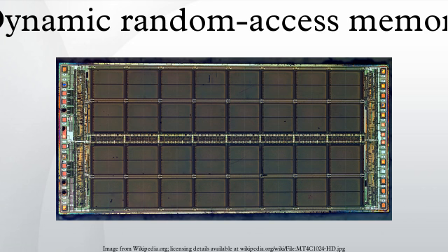BEDO also added a pipelined stage allowing page access cycle to be divided into 2 components. During a memory read operation, the first component accessed the data from the memory array to the output stage. The second component drove the data bus from this latch at the appropriate logic level. Since the data is already in the output buffer, quicker access time is achieved than with traditional EDO.